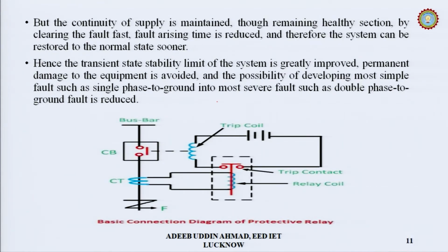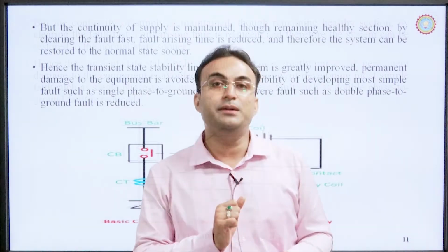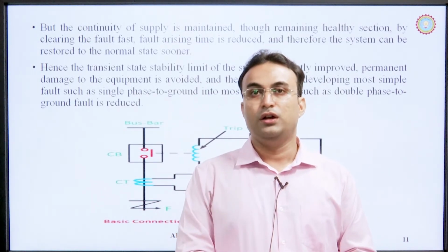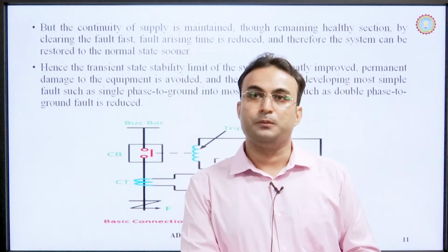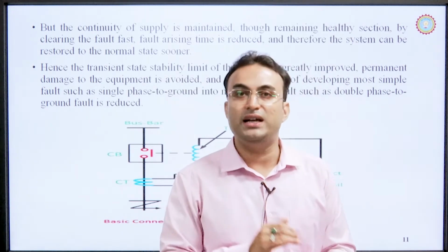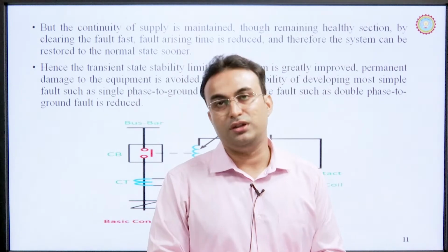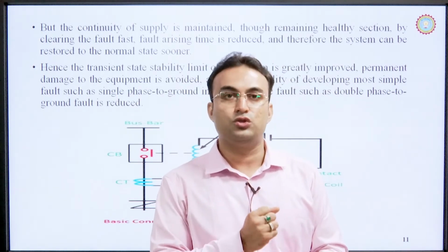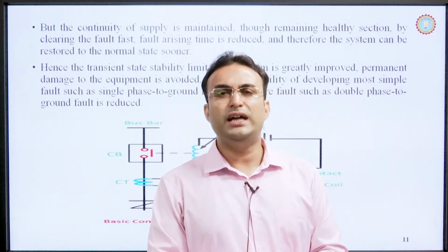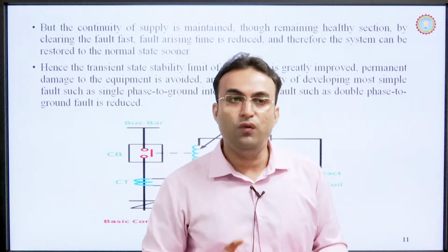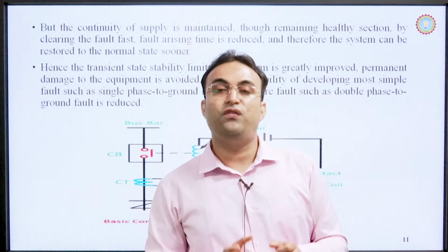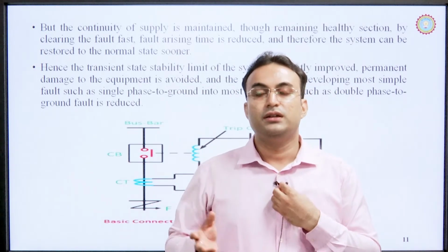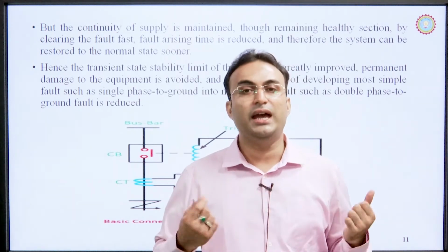Now, the continuity of the supply is maintained, that is very important, that the continuity of the supply is always maintained through the remaining healthy section. By clearing the fault fast, arcing time is reduced, and therefore, the system can be restored to the normal state sooner. So, that is very important, how quickly we can detach or separate our faulty section from the healthy section.